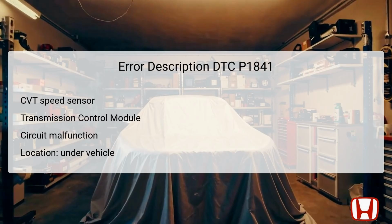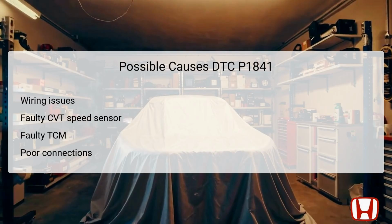The TCM, located often in the engine bay or under the dashboard, acts as the computer brain of the transmission, interpreting inputs from various components. If the sensor's readings do not match the expected parameters for reverse gear operation, the TCM flags the issue by storing the DTC P1841. The causes of DTC P1841 can stem from several issues.